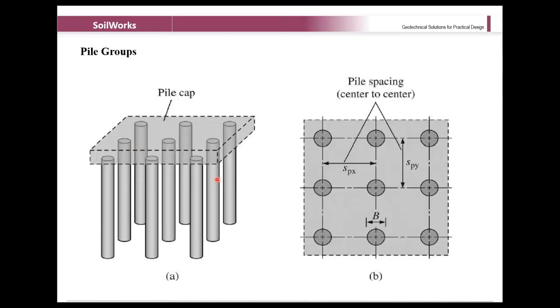That's why in most of the cases pile groups are used, and a single pile with a pile cap is very less used. And suppose let's say we are into a pile raft foundation. So we got a very huge pile cap, and underneath it we got, let's say, 100 piles, such a number of piles. In that particular case, 25 to 30% of the load coming from the superstructure will be taken by your raft, and then the rest will be transferred towards the bottom, that is your pile foundation.